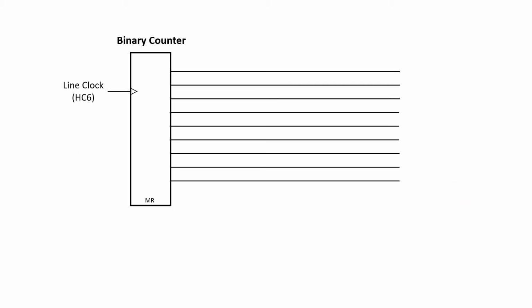To build this, I need a binary counter that can count to 262, so I'm going to need 9 bits. This will take 3 of the 74HC393 counters, so 2 chips in total. In character mode, the first 3 bits of the count are used for the line position within a character, and so Steve Wozniak labelled these VA, VB, and VC in the Apple II. So I'm just going to stick with this convention. The next 6 bits are character row, and they're labelled V0 through V5, and I'll use these as well.